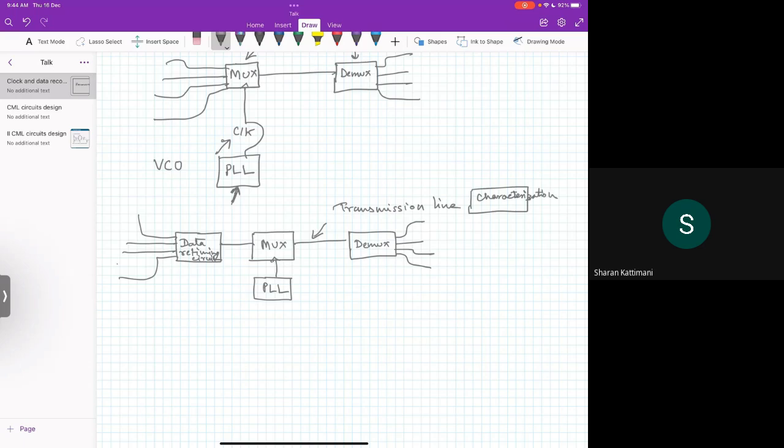Okay, apart from that, it is 50 ohm edged, so you need to put another block here that will act as a buffer and also 50 ohm matching. You can say a buffer to drive this transmission line plus 50 ohm matching combination.